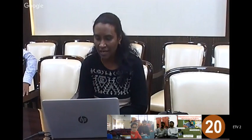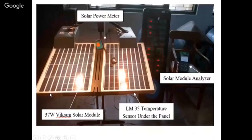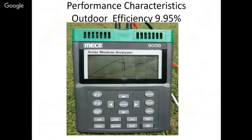Under this panel we kept a thermometer, or you can use an LM35 or some other sensor. We measured the temperature under the panel, measured the irradiation the same way, and entered both into the solar module analyzer. I can show you the picture of the solar module analyzer. Once you enter them, it automatically gives you the characteristics.